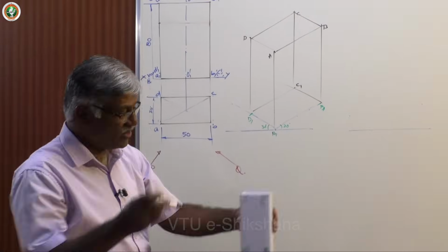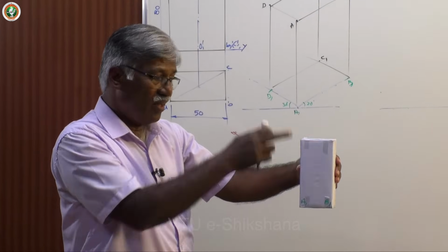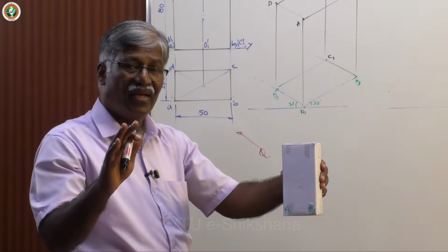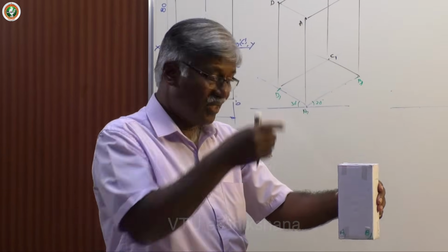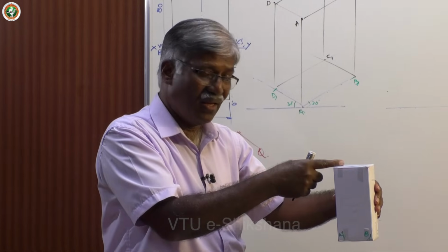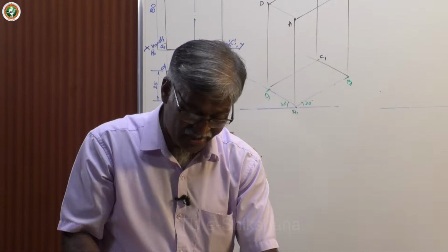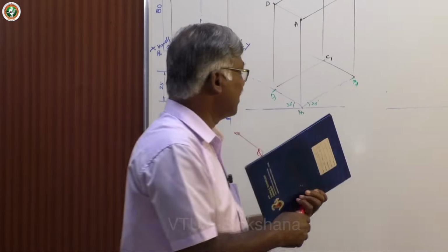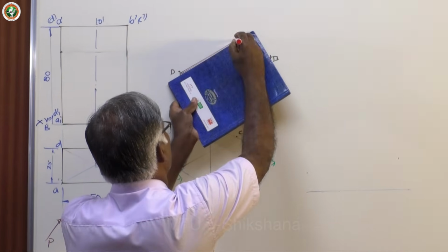Now, if you look from this direction, the base is not visible. The nearest key surface is the top face. It is the same as the projection of solids, key surface reference. The nearest surface is visible, the boundary line is visible, the base is not visible. So, let us do that job. Keep all the visible edges. The visible key surface is the top face, fine.